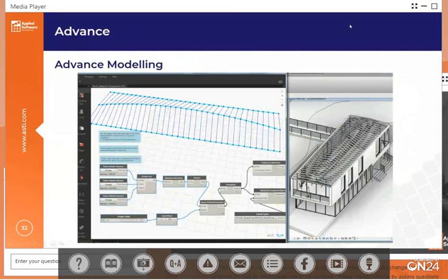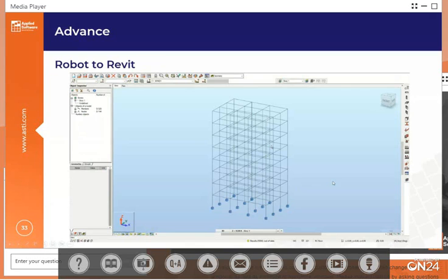All right. Next, we have some advanced modeling. This one I don't have a video. I'm just showing you. This is not something I've done. This is actually what Marcello depicted in PAS, I think, Autodesk University. But it shows you some advanced modeling. So in this case, the architect really wanted to make it a good challenge for the structural engineer by making this kind of curving roof here. And then you could utilize Dynamo to help build that for you, so you're not putting in each individual beam by yourself, which takes all the time.